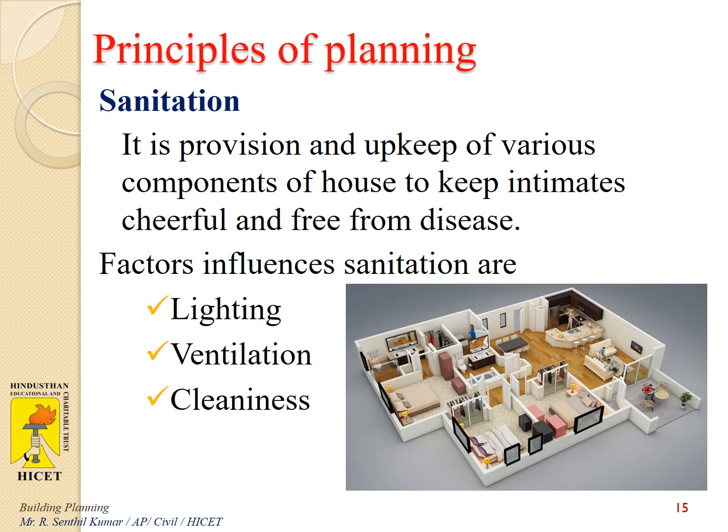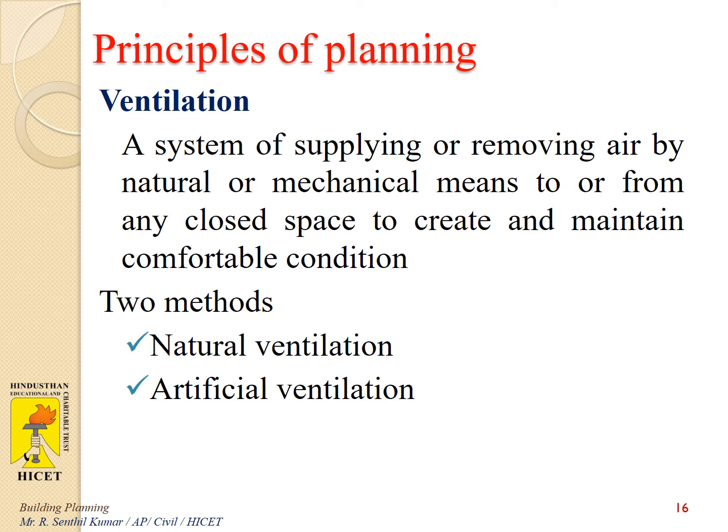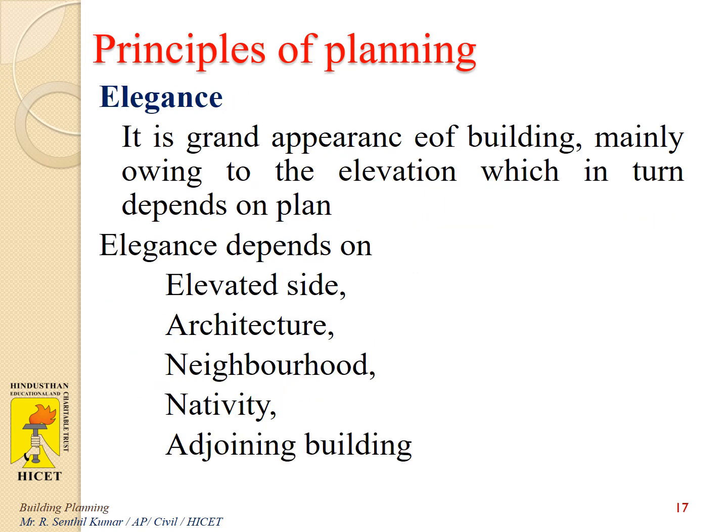The lighting, that is natural sunlight or artificial, and the intensity of natural light is affected by pollutants like smoke, dirt, dust, gases and clouds. Ventilation means reduction in humidity and removal of heat, and proper supply of oxygen, naturally or artificially. The orientation of the building and the location of windows help to provide proper ventilation.